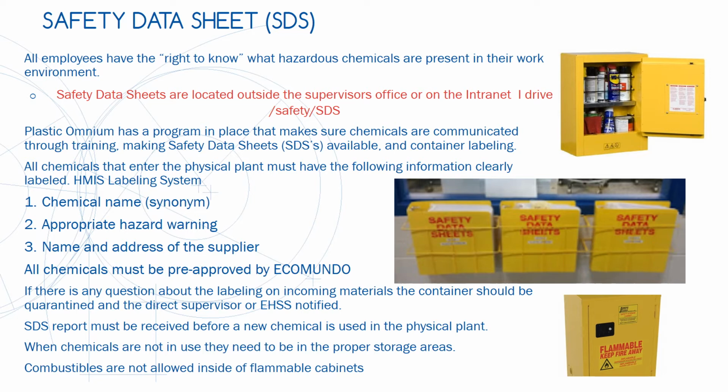An SDS report must be received before a new chemical is used in the physical plant. When chemicals are not in use, they need to be in the proper storage areas. Combustibles are not allowed inside of flammable cabinets.